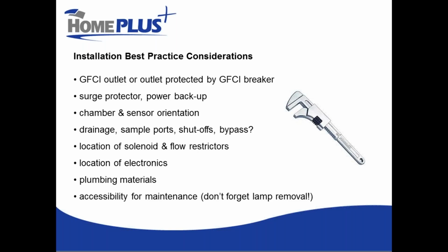Chamber and sensor orientation matters. So generally speaking, for most UV sterilizers, they should be installed vertically rather than horizontally. And the chamber orientation, if it is permitted to be horizontal, there can be some problems associated with the sensor being either on the top or the bottom of the chamber.